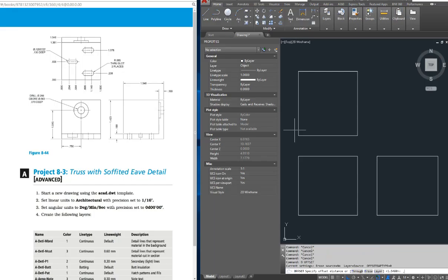So I'm going to offset 0.294 from, now you got to kind of keep track of what you're doing, and I'm going to offset 0.544, and I'm just going to move from the left to the right, always offsetting from the far left because it's datum dimension from the 0. And then I'm going to offset, what's that say, 0.899 from here to there, and I'm going to do it again, 1.149 from here to there.